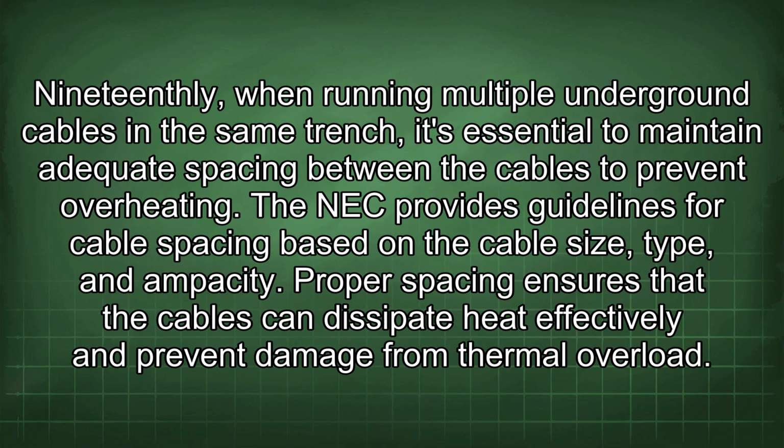19thly, when running multiple underground cables in the same trench, it's essential to maintain adequate spacing between the cables to prevent overheating. The NEC provides guidelines for cable spacing based on the cable size, type, and ampacity. Proper spacing ensures that the cables can dissipate heat effectively and prevent damage from thermal overload.